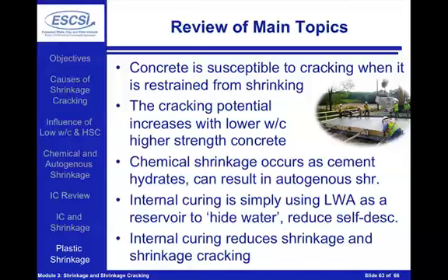We frequently see a rise in the cementitious content, which can be a rise in paste. And we can also see many times the pore structure being modified to have a smaller particle size distribution. And this really leads to that rise in autogenous shrinkage. Chemical shrinkage occurs as the cement hydrates. Chemical shrinkage is the total volume change. The external portion of this is known as autogenous shrinkage.